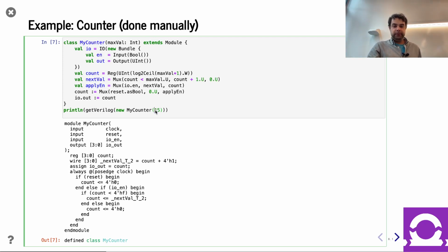That's going to only require 4 bits. So we have a 4-bit counter. All cool. Now, of course, if we went one smaller, we would still have the exact same situation. Now, if we went one bigger, then we're going to wrap over and get another bit.